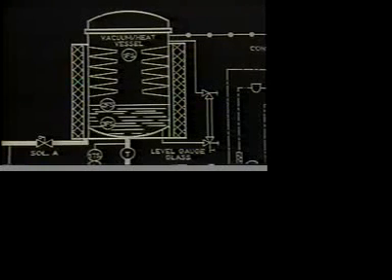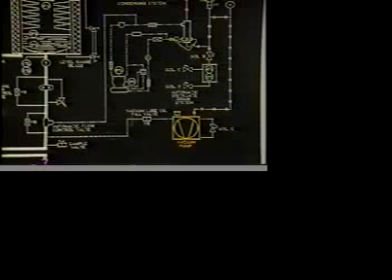The lube oil, which is contaminated with water and perhaps some gas constituents, is now flowing on these baffled or slanted trays. Since this entire region exists at a vacuum and at elevated temperature, the liquid water will now flash off, and it can be pulled off by virtue of the vacuum pump, which we see over here.